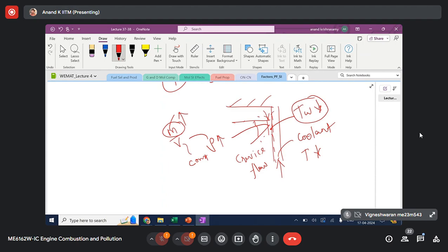When the crevice flow mass is increased, its contribution to HC emission will increase, because more mass charge goes into the crevice region with lower coolant temperature. And the other effect we discussed was adsorption and desorption from lube oil, right? So in the boundary, you will have a lubricating oil. When the temperature drops, what will happen to the viscosity of the lubricating oil? Can I say it is higher?